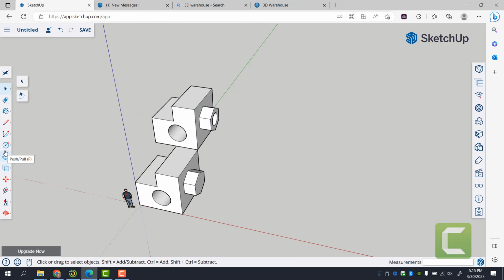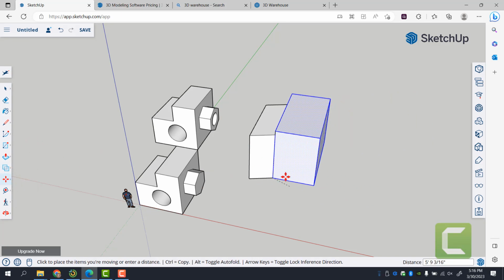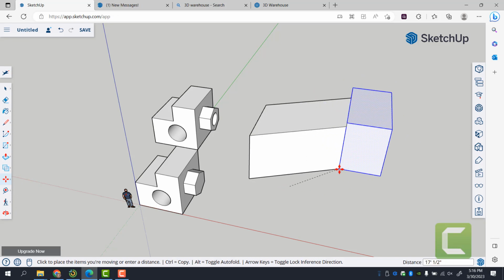Now, another feature inside SketchUp is the ability to make components, which are pretty much known as blocks or families in Revit. So blocks in AutoCAD, families in Revit. I'm going to go ahead and use the rectangle tool again, and we're going to extrude another prism. So when I extrude this prism, if I was to attach anything else to it, if I was to push something along and move it, notice despite that being an individual object, if I decide to move it again, it is attached to the square. They are not individual groups.